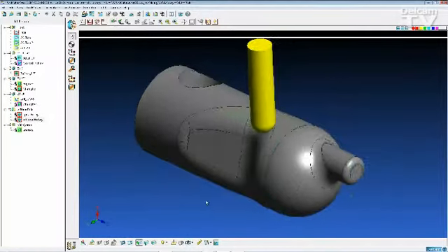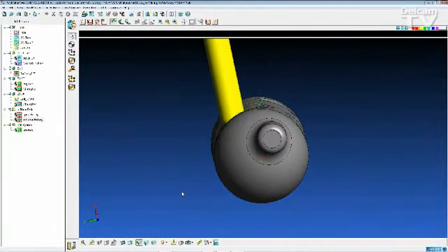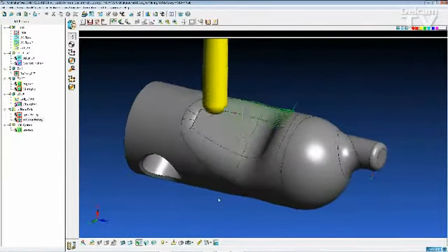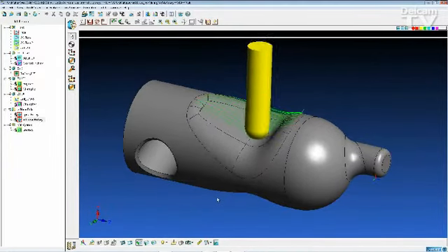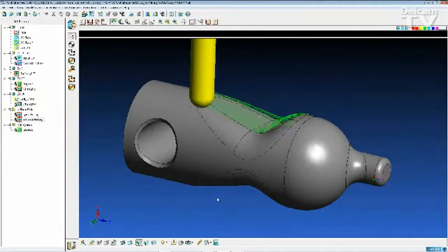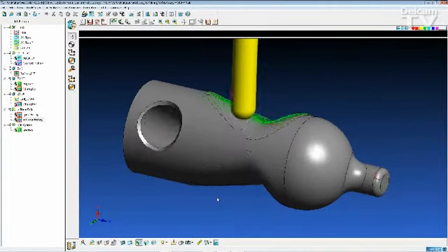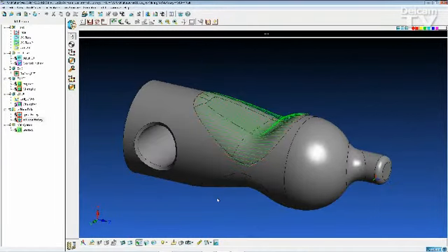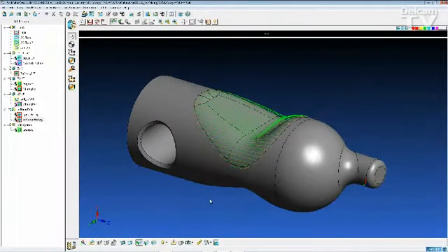And we'll take a look also at linear. So linear is doing a rotary toolpath, but it's cutting along the part rather than around the part. So cutting back and forth, again with the tool offset in the Y-axis to get good surface footage for rotary toolpaths.